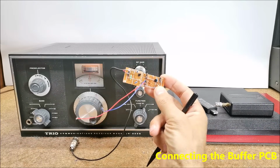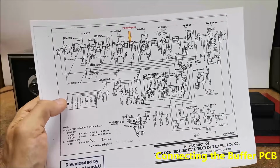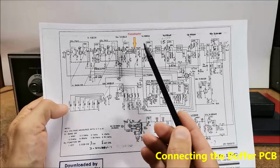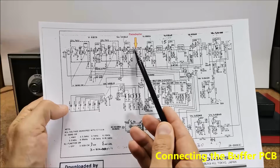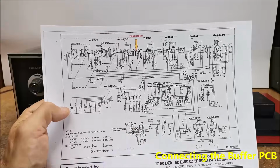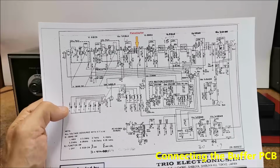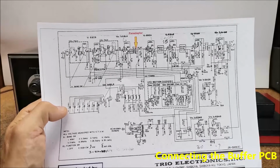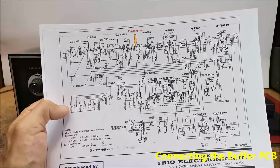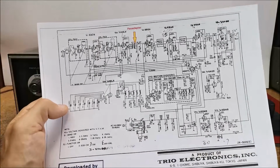Regarding the connection point of the Panadapter, this is the schematic of my radio, and the board should be connected immediately after the first IF transformer, IFT-1A, at the point marked with this yellow arrow. The board should be mounted as close as possible to this point so that there is no additional interference due to the length of the cable. In almost all superheterodyne receivers, the Panadapter should be connected immediately after the first IF transformer.